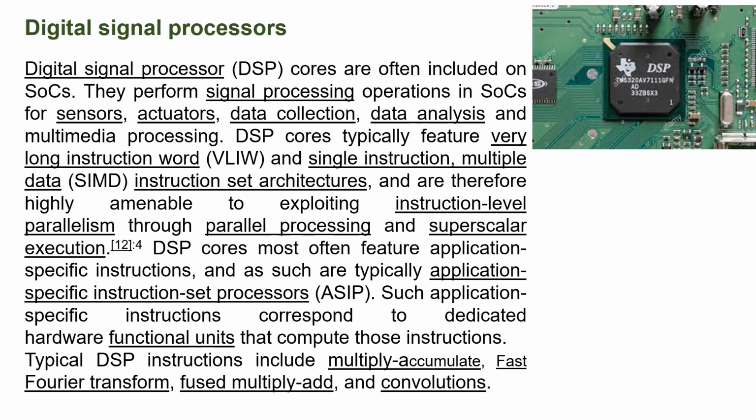For all these purposes, extensive mathematical computations have to be carried out, and those can be carried out with the help of a special type of processor. A simple microprocessor cannot be used for this. It will take a very, very long time to implement these mathematical operations. So a specialized processor which follows a special architecture is used as the digital signal processor core.